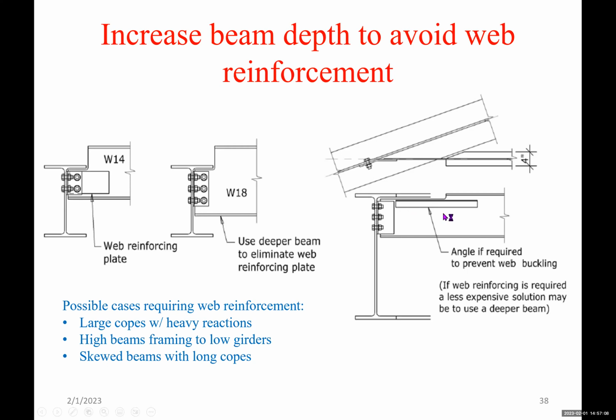If you have to cut part of the flange, then of course you have to reinforce it, if you have elements coming at a really sharp angle, like we have here.